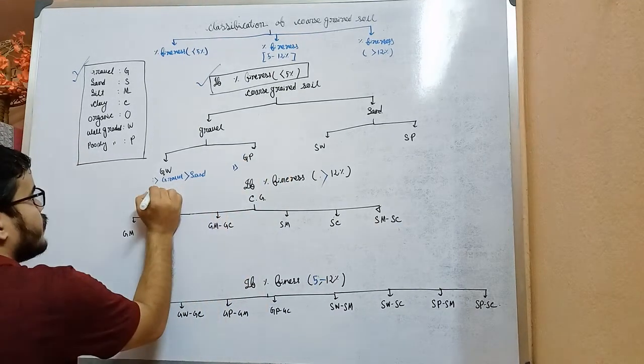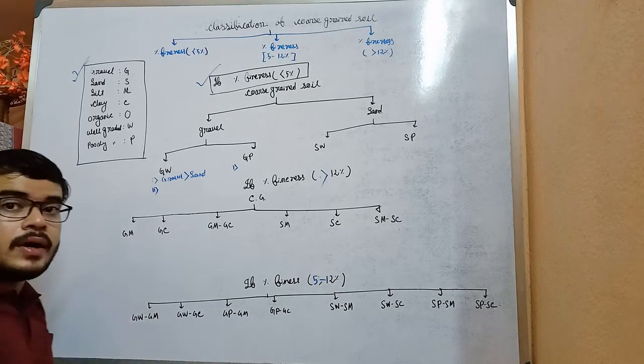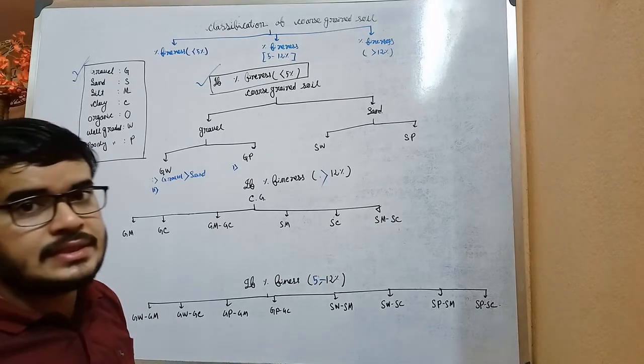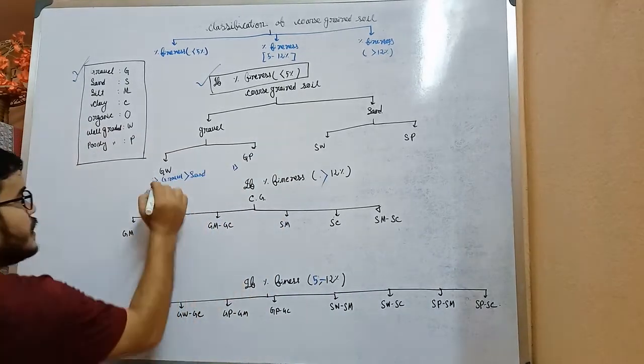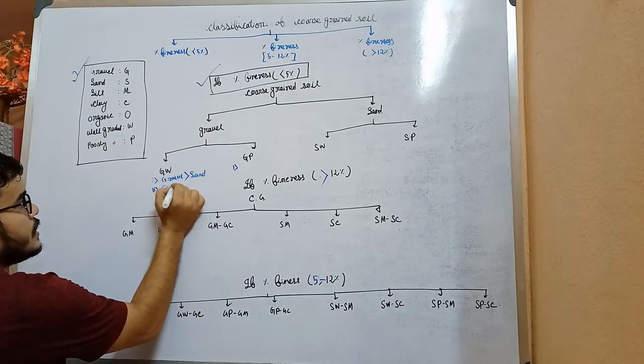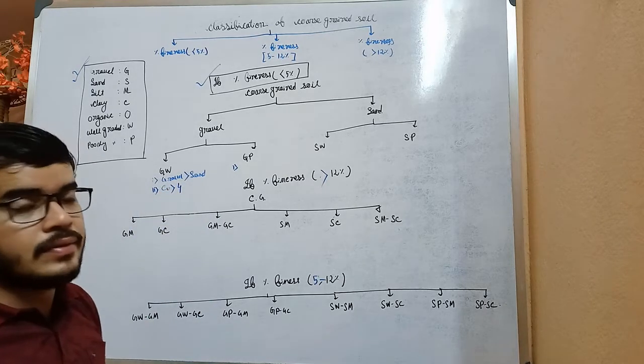Okay. Number 2 will be the shape factor that we have learned, Cu equals d60 by d10. So if Cu is greater than 4, it will be well graded gravel.